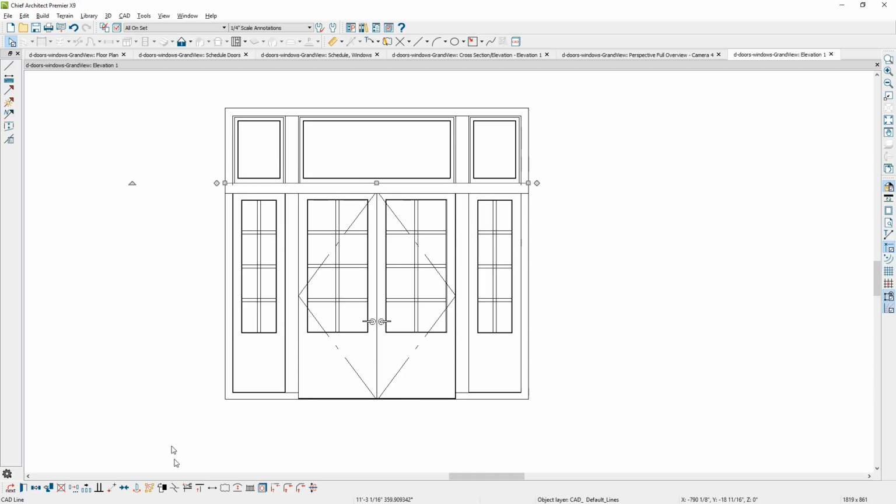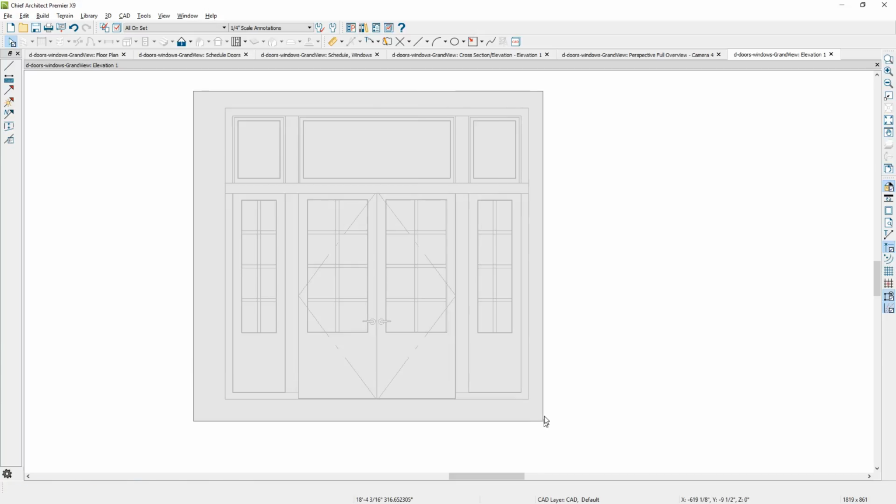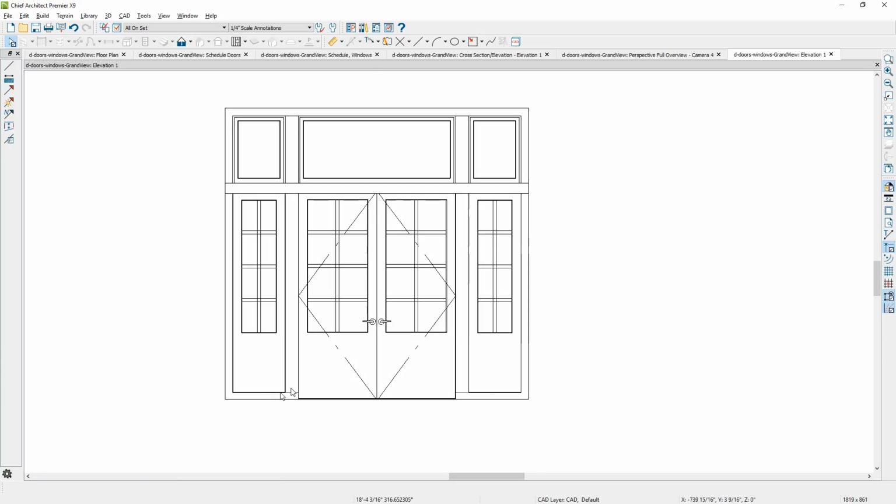Again, select the line, use the trim tool, and I'll clean up those extra lines real quickly. Drag that right through there, any of the lines touching. Now I've got the view that I'm after. A lot of times what I'll do, this is good enough, but I'll draw a marquee around this and block it so that I don't have a problem accidentally deleting any of the lines. Now that that's blocked, I can actually send that out to the layout.